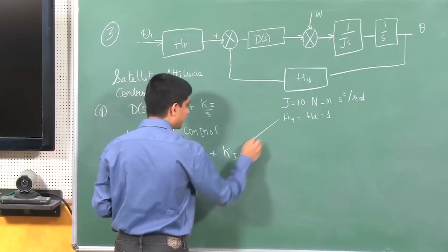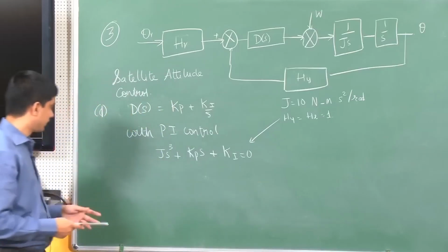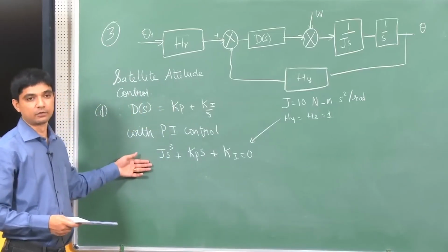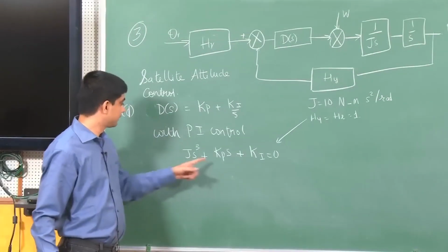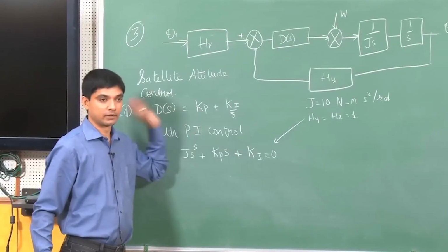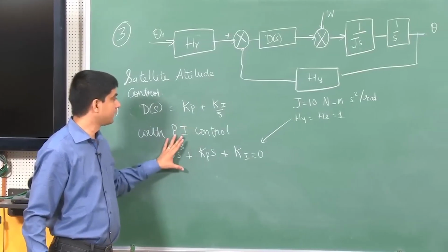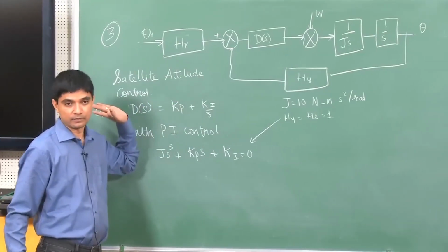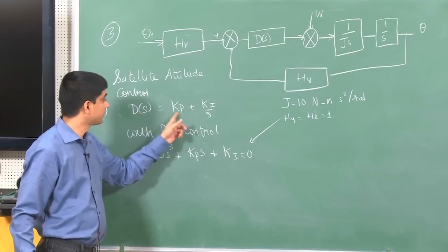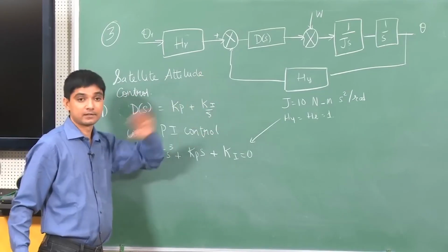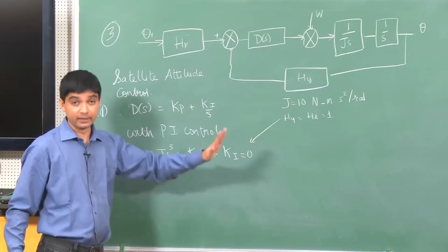This is again assuming this to be true. Okay. Now this is unstable, right? I don't really need to analyze this any further. So with the PI controller I know it is unstable. Now it doesn't really help me to compute the steady state error anymore, because whatever I do, the system is unstable. Therefore, just doing a PI control and then doing the steady state analysis is really meaningless.